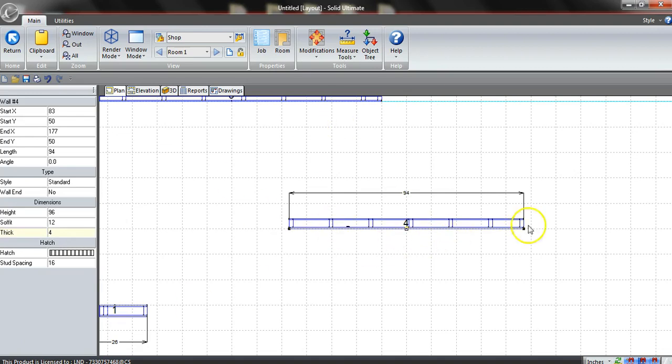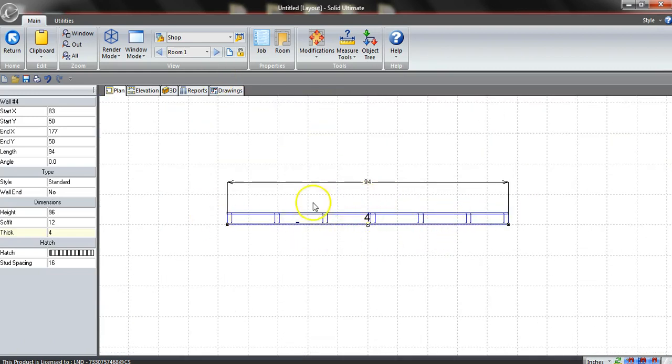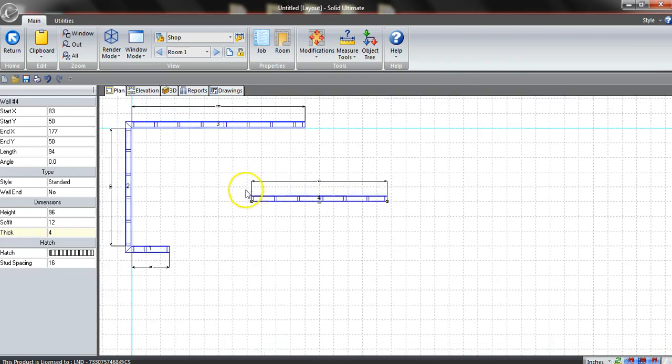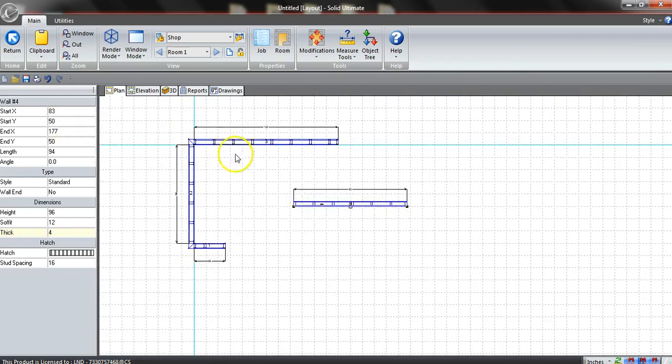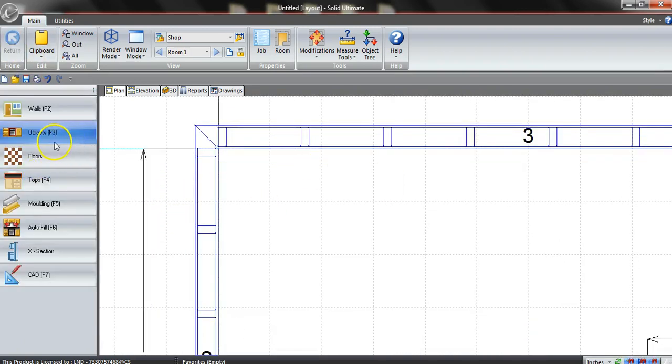Okay. Because we're going to have, like, for plumbing and stuff like that, if there is plumbing here, which there won't be for this island, but just for almost every island, I keep 4 inches between the set of cabinets facing this way and that way, especially if these are 24-inch over here and these are 14-inch over here. You'll see. First off, like every other kitchen on the planet, we're going to start in the corner, and we're going to do a lazy Susan.